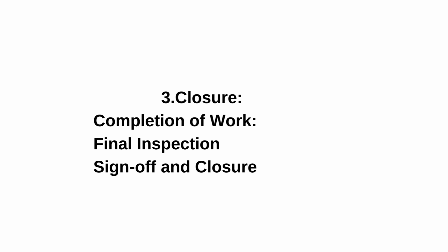Once the authorized work activities are completed, the permit receiver must ensure that all equipment is properly secured, work areas are cleaned, and any waste or debris is appropriately disposed of. Whatever changes we made at the workplace is reverted back to normal. After that, a final inspection may be conducted to verify that the work has been completed as per the permit conditions and there are no remaining safety hazards.